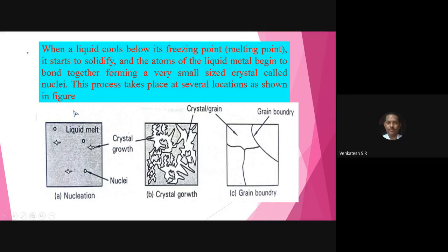In three directions, nuclei form, grow in size, attract the neighbor nuclei and form the crystal. Again, formation of the crystal, then the crystal grows in size and reaches the maximum size, that is called crystal growth, and the maximum size is called the critical size of the nuclei.